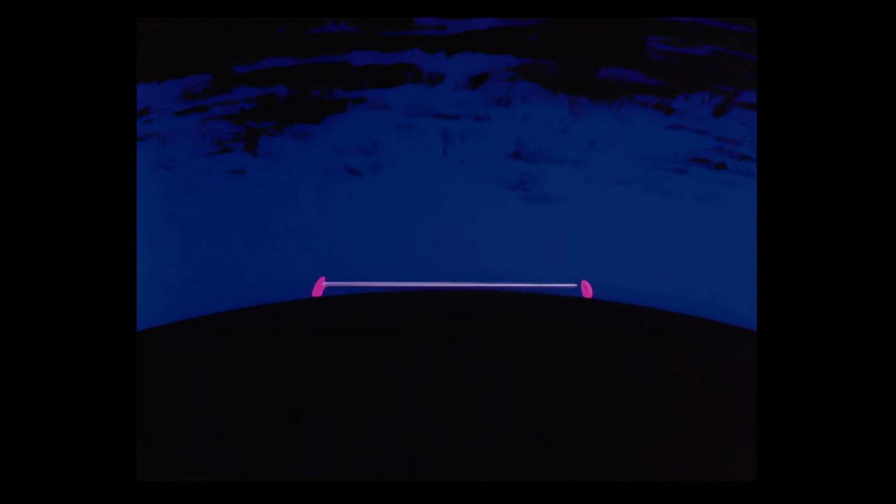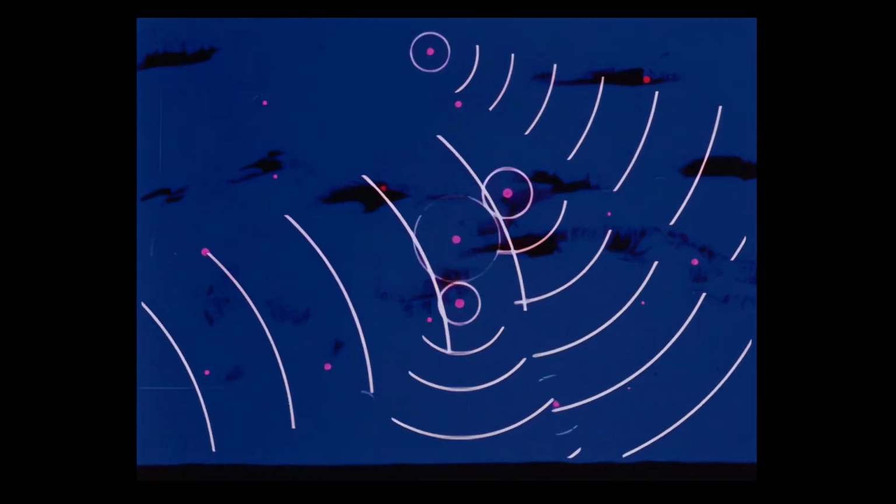The line of sight system gives high traffic capacity over short distances. Range can be greatly increased with the tropospheric scatter system. In this system, the beam is directed at the horizon. Its energy is then re-radiated by the millions of particles in the atmosphere. This re-radiated energy is picked up by high-gain dishes.